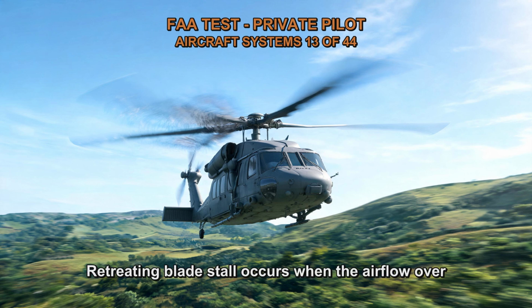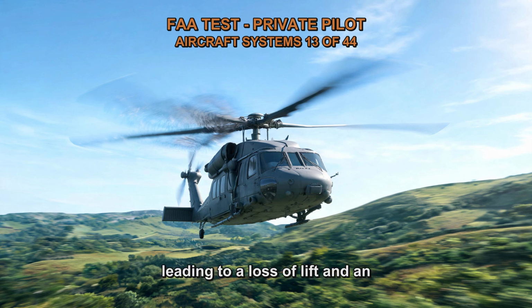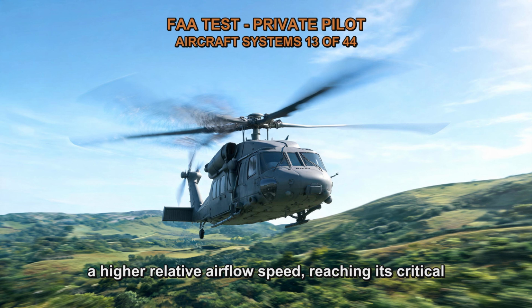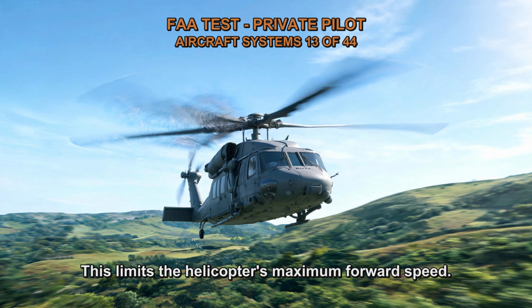Retreating blade stall occurs when the airflow over the retreating blade becomes insufficient to sustain lift, leading to a loss of lift and an increase in drag. As forward speed increases, the retreating blade encounters a higher relative airflow speed, reaching its critical angle of attack and stalling. This limits the helicopter's maximum forward speed.